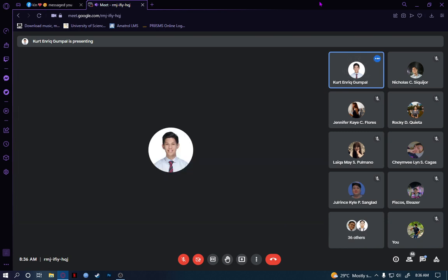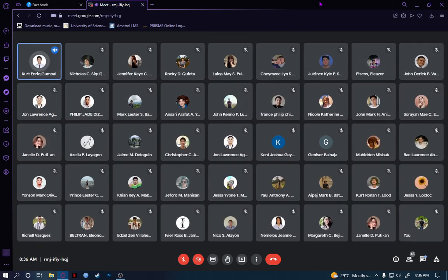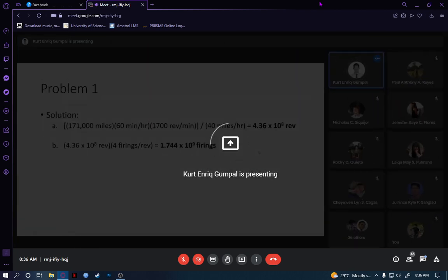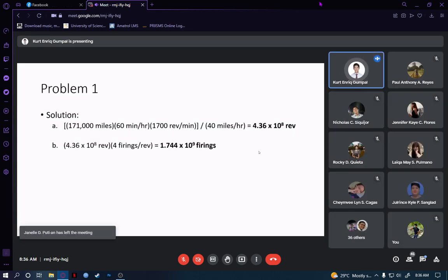Is that clear? It's difficult since I'm online, it's hard to draw. So that is 4.36 times 10 to the power of 8 revolutions times 4 firings per revolution. Again, 4 firings because I have 1/2 per revolution times 8 cylinders, which is 4. Four times, the spark plug fires.